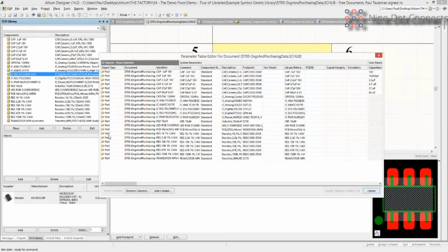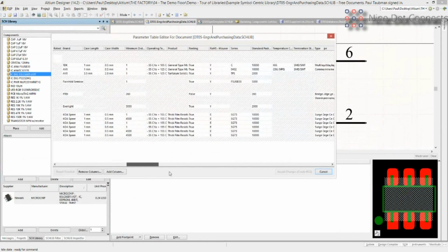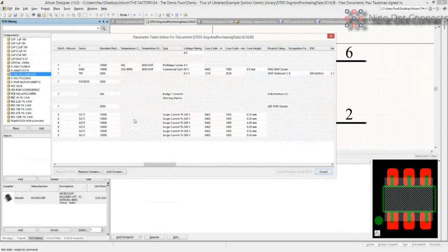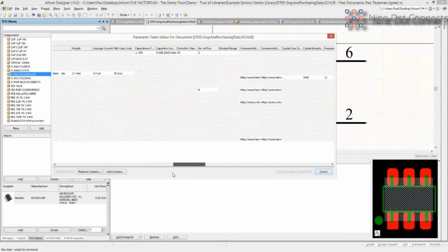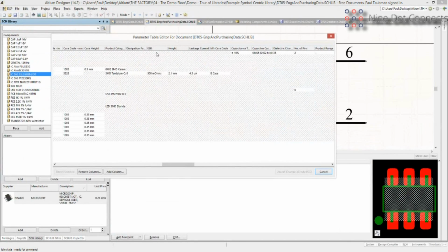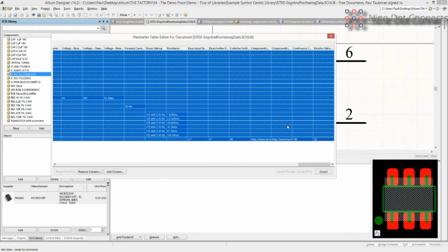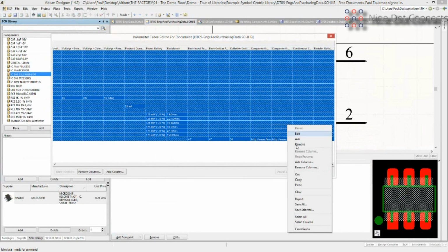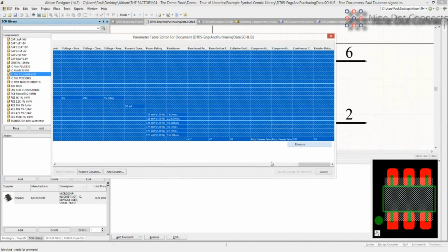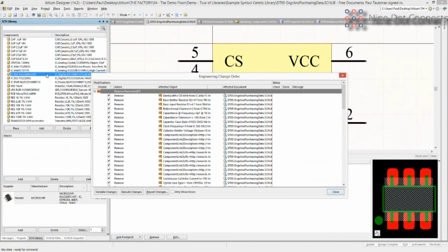Right? And this allows me to do edits as I see fit. So if I did get supplier information, I pushed it in over there, and I do this for all the parts, then I can see what I've accumulated as a result of that. All right. Now, for example, if I don't want any of this stuff, let's say I don't want this one over here, I can click on this here, and I can go onto this one over here, hit the Shift key, and I can tell Altium, hey, go ahead and remove this. And Altium will basically remove that, and then it will say accept the changes, and it will push that stuff in automatically. So you don't have to make changes to each and every single one of those. All right, and that's what I've basically told it to do right now.